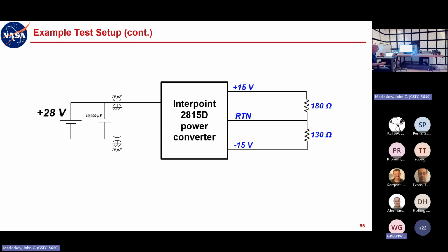John, yeah. What I would say about that, because your setup looked like you still had the sponge on those 3 wires leading up to the load box, my thought was that you have common mode flowing on both the plus 15 and minus 15, and they would typically return through the return because that's the only path.